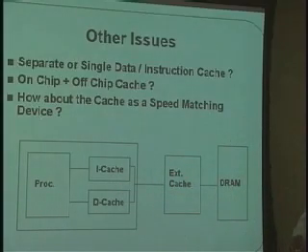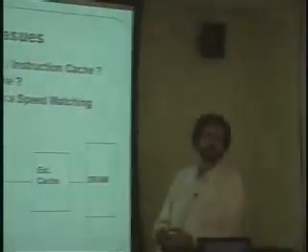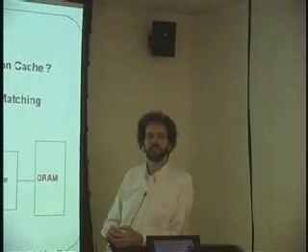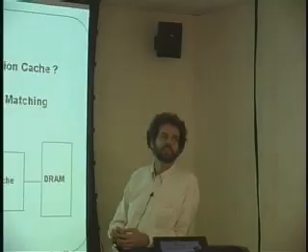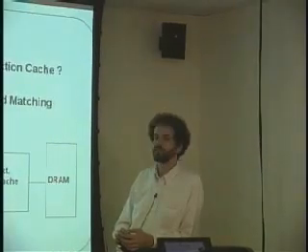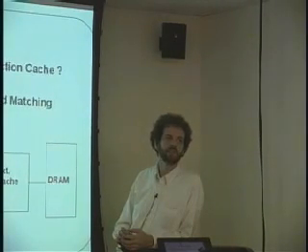If they are separate, are they generally equivalent sizes, or is the data, for example, twice as big? That's an excellent question. In the machines I've seen, the instruction cache is bigger. And the reason is, again, the machine has a voracious appetite, and it's executing opcodes like crazy, okay? What it's not doing is executing loads and stores on every opcode. And so you typically see that the data cache is smaller than the iCache.